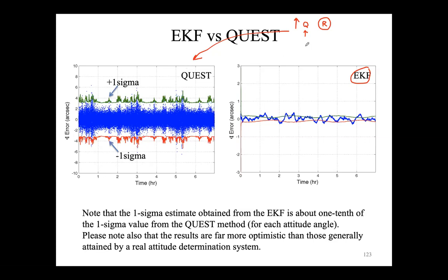The other problem that you can have is that the Q is too low compared to R. So it's always larger, but probably is very close to R. What can happen is that you're going to have a complete divergence. For example, you're going to see that your errors converge to a biased solution. So the tuning is important.